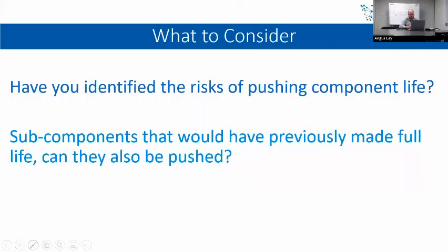When you remove a component for PCR and it goes off for rebuild, on a component that's made for life, you need to get those teardown reports from the OEM to understand that condition and determine whether or not you can safely push that component further. If it is received in a condition where there are critical issues, then potentially you're already pushing as far as you can.